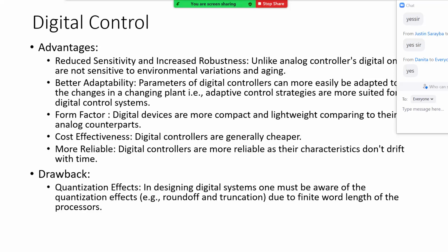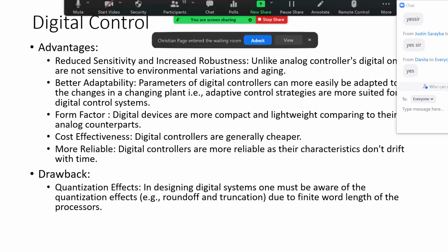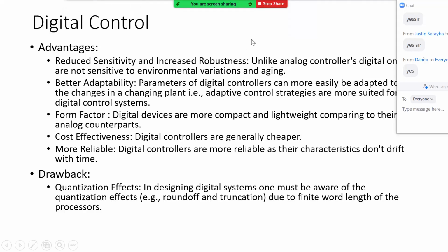Think of any analog signal. If you add any noise to that signal, you cannot differentiate the original signal from the new signal. Take a digital signal that is a 1 or a 0. For instance, if this digital signal is below 2.5, it's a 0. Above 2.5, it is a 1. The signal can be 0, 0.1, 0.2, 0.3, 0.4, 0.5, and still be decoded as a 0.